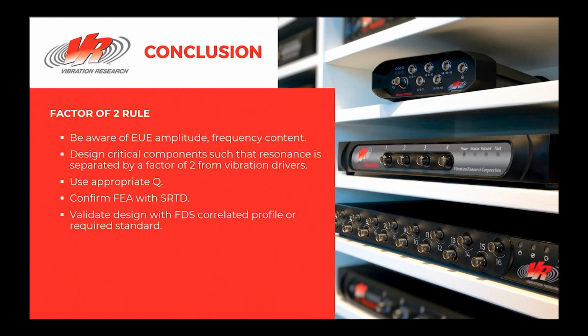We use this information to design resonant-resistant products and to develop vibration profiles based on correlated fatigue damage spectrum. We should design critical components such that resonance is separated by a factor of 2 from vibration drivers. Use appropriate Q when performing analyses. As Q increases, the factor of 2 rule has even greater forgiveness.